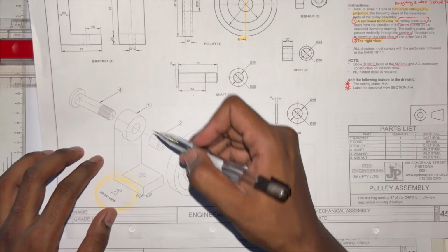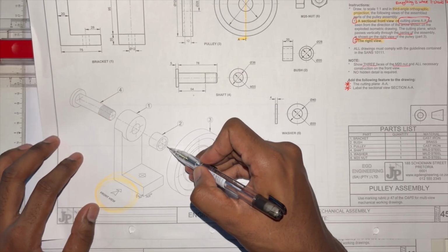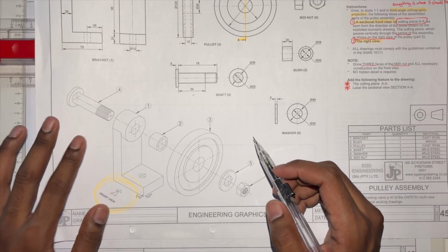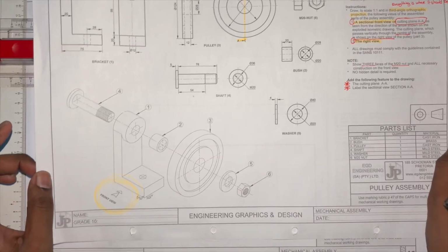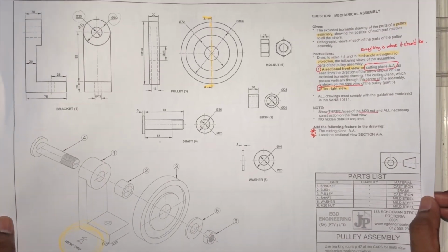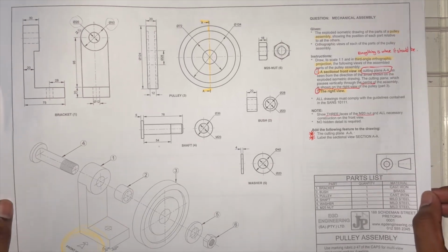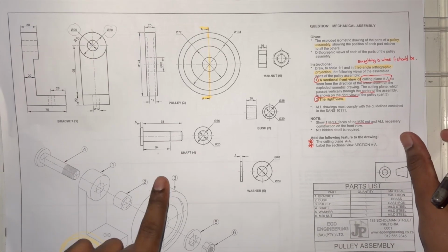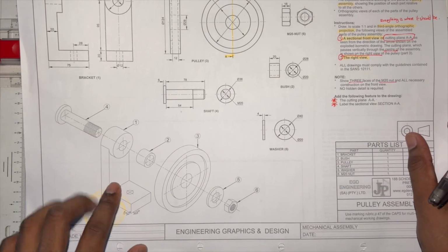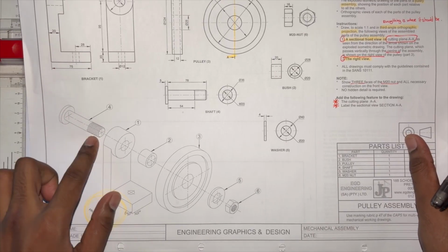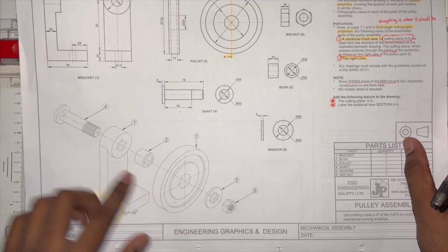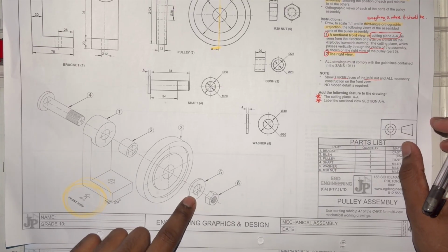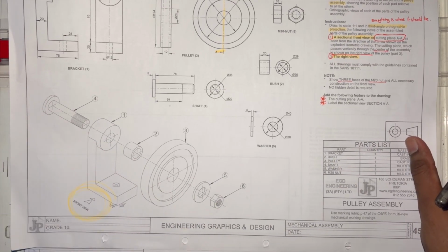Well, not the shaft. We don't cut the shaft. The bush, straight down, straight through. Not these two either. So if you want to know what to cut and what not to cut, at the first page in this section, the very first page of casting, mechanical drawings, there's a set of rules that tell you what you should cut through and what you shouldn't cut through. So revisit those. We don't cut through ribs. Depending on how you cut a shaft, we will either cut it or not cut it. Longitudinally, we don't cut. Latitudinally, yes, we do. We never ever cut a washer or a nut.